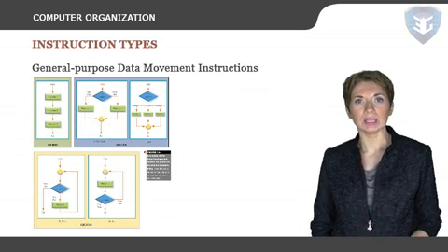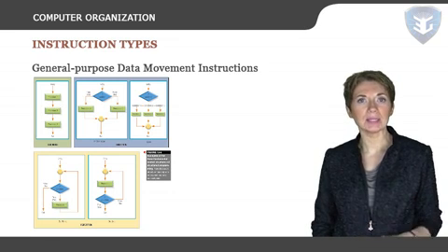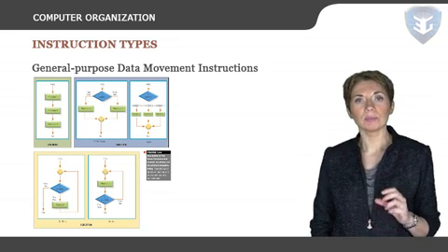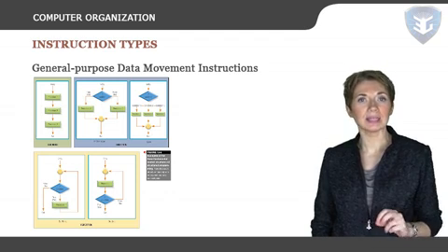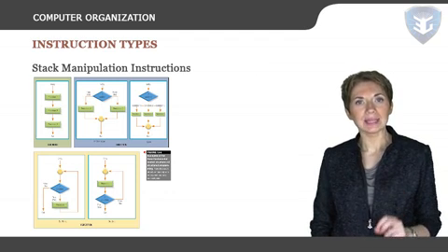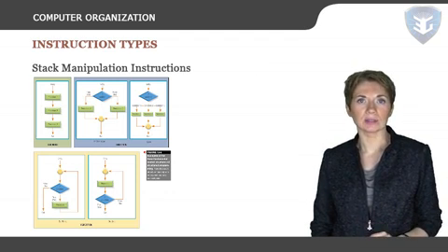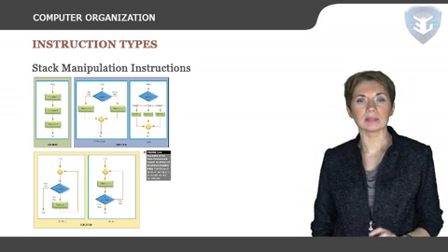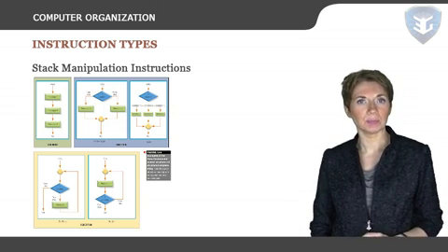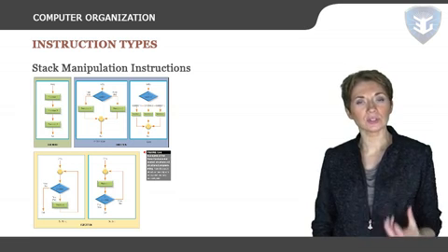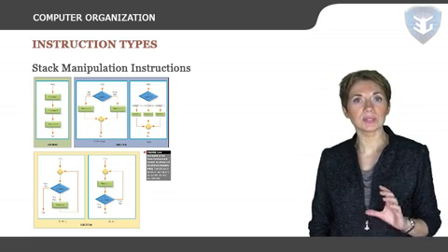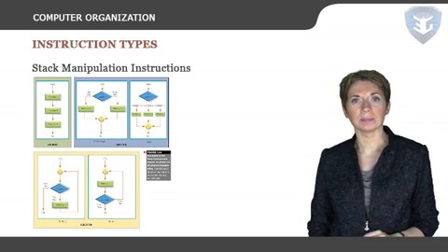The MOV, move, transfers a byte, word, or double word from the source operand to the destination operand. Stack manipulation instructions. The PUSH decrements the stack pointer, ESP, then transfers the source operand to the top of stack indicated by ESP.